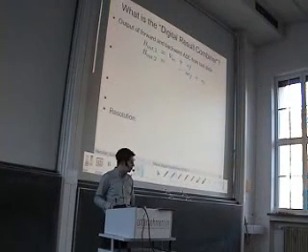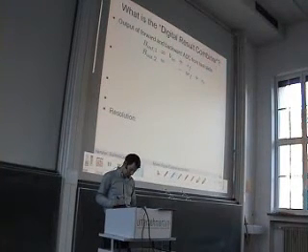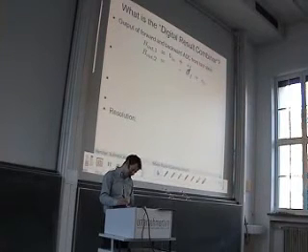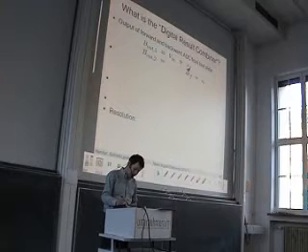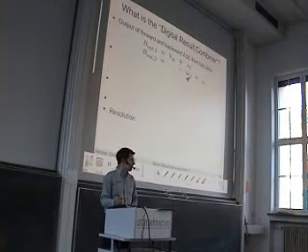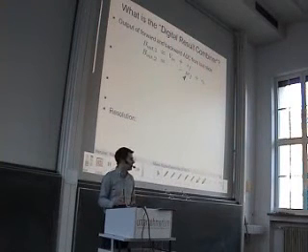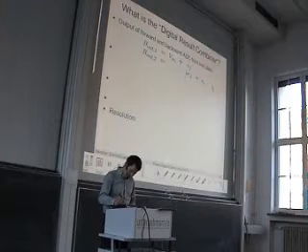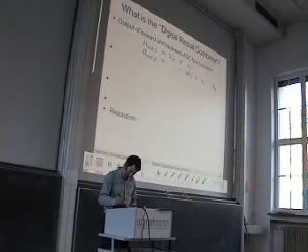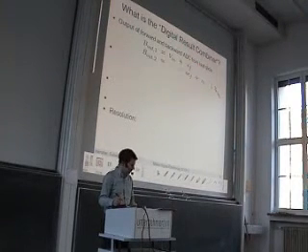Here I copied these two formulas. So what we can do is to say, well, we have the EF visible at the output of the first stage, and we have the EF visible at the output of the second stage. Well, here is a factor of A, but it's the same quantization error. So what we could do is to say, let's multiply this by a factor of 1 over A and add it to the first output.